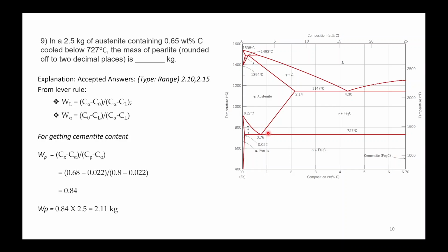It also depends on whether you are looking at the iron carbon diagram. In that case, you'll be getting the equilibrium diagram, which will have graphite forming, so those lines will be different compared to these lines as well. And as I told earlier, 0.76 is also told as 0.8%. It is rounded off in various books, or it is told differently in different books.